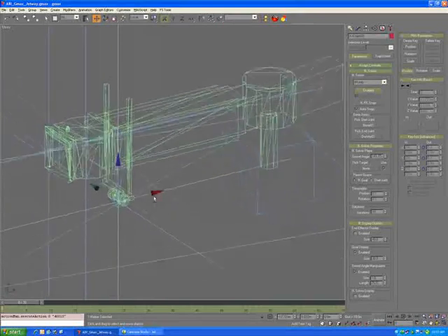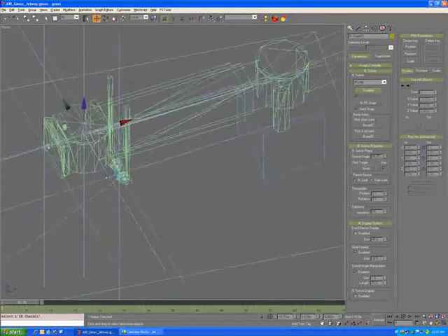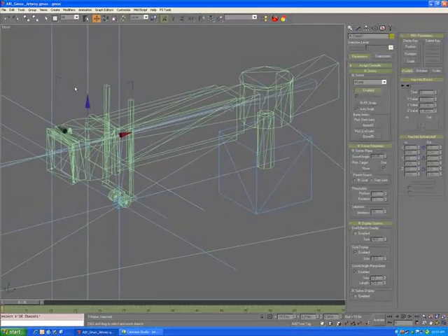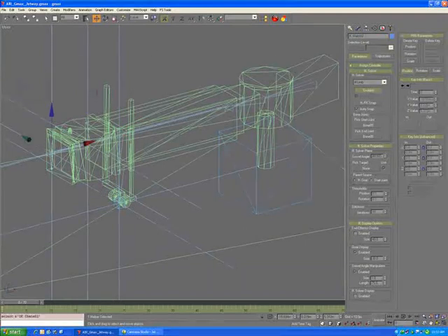So it is important that the IK handles have the correct names, because actually we use the names of the IK handles to determine what happens with them. So this first IK handle goes to the outside of the aircraft. This is called IK main handle. So it's IK space main handle, just like that. The next IK handle, which is the one for the mouth of the jetway, is called IK secondary handle. Once again, IK space secondary handle, just like that. And the last IK handle is called IK space wheels ground lock, just like that.